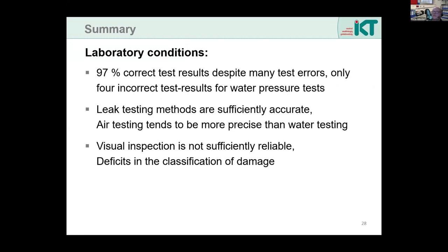There you have to know that when you make air testing, it's a little bit difficult to tighten the bubble to an old pipe wall. Under the laboratory conditions, we had new pipes with very smooth pipe walls, and when you go to the practical side, it can tend to be more difficult.